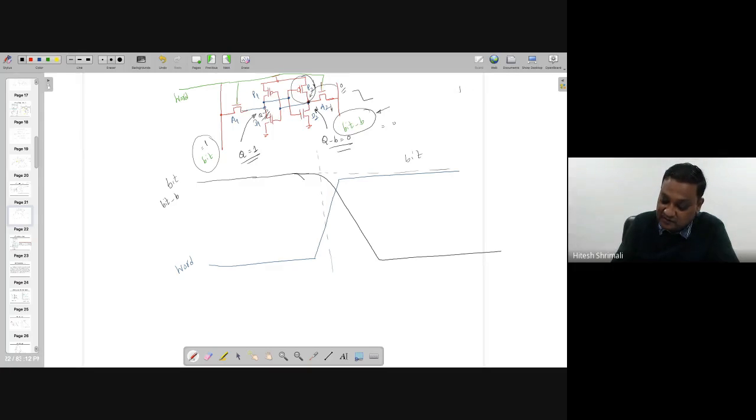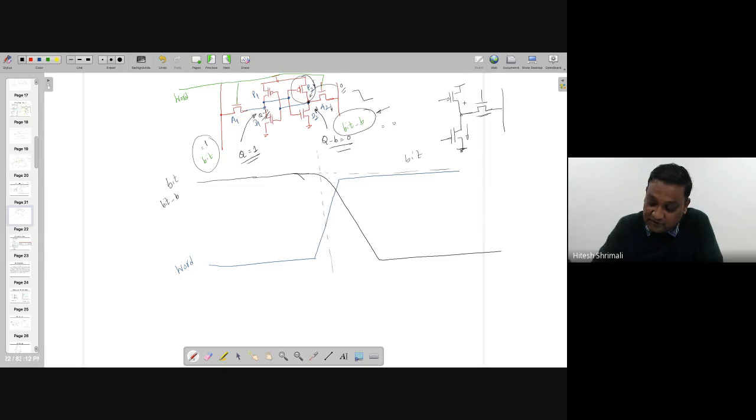Right now there were 3 possibilities. Right. So let's assume that when you were writing it earlier, this was 1. So in that case, there are 3 different transistors here, maybe partially on, maybe fully on. So if they are partially on, in that case, these two are playing the role over there. Even if you'll make sure that this transistor is off by making sure that Q equal to 0, even if it is earlier state, then these two transistors will be there, which are fighting with 2 voltages, bit bar equal to 0 and VDD equal to 1, right? So it's actually fighting between these two.